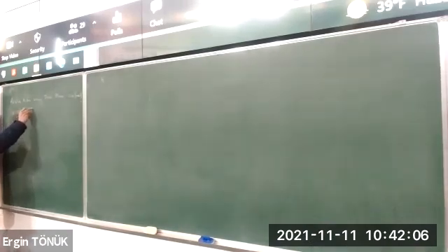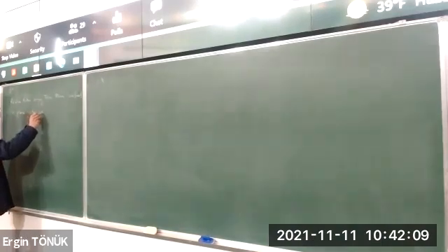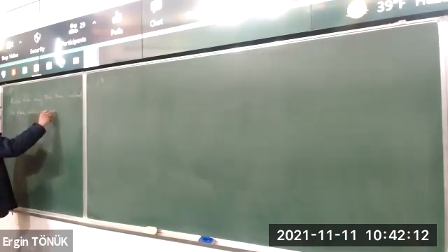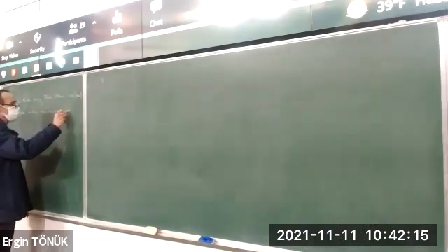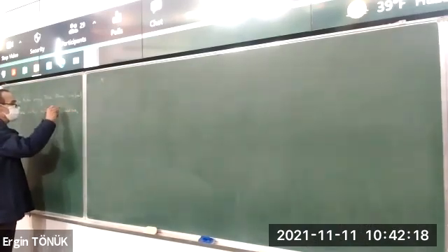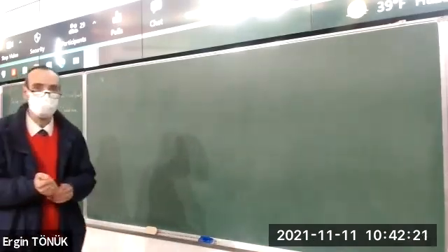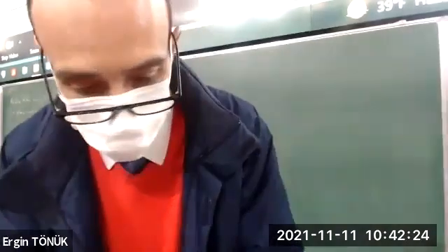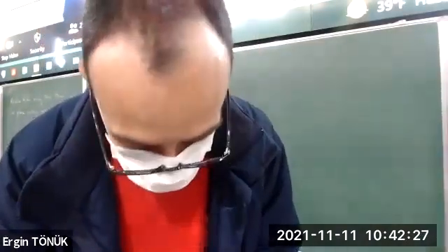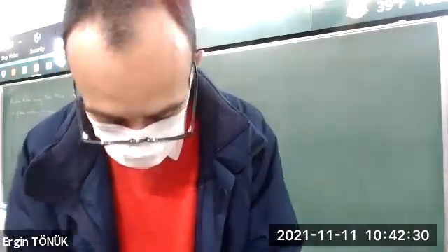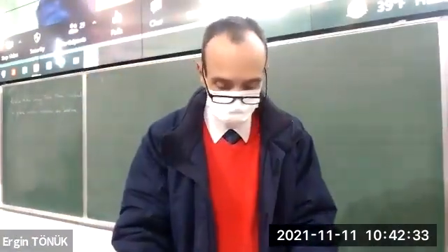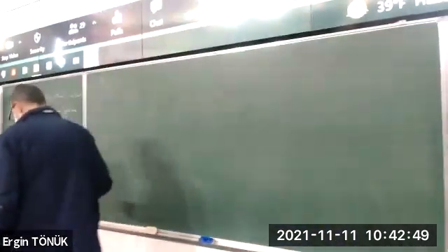Plane motion, rotations, add. Of course, when we say add, we have to consider the sign. That is, if counterclockwise is positive, then clockwise is negative. So, if we have the motion of two planes relative to a fixed plane, we would like to determine the relative motion between the two planes.